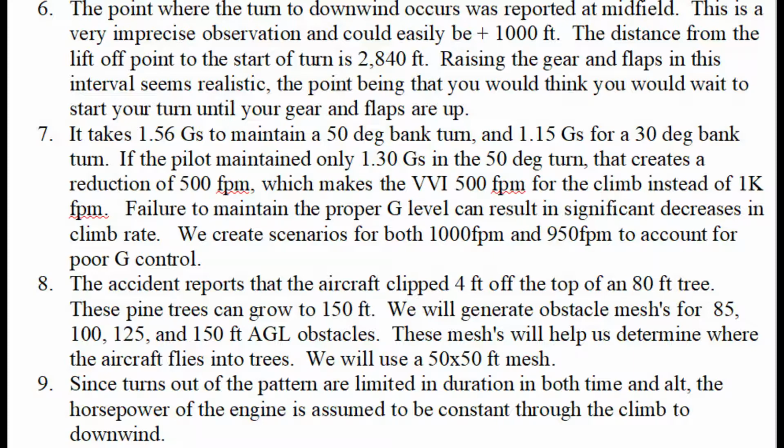The accident reports that the aircraft clipped 4 feet off the top of an 80-foot tree. These pine trees can grow to 150 feet. We will generate obstacle messages for 85, 100, 125, and 150-foot AGL obstacles. These meshes help us determine where the aircraft flies into trees. We will use a 50 by 50 foot mesh.